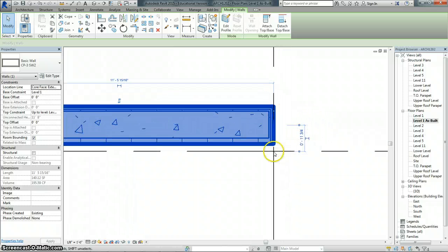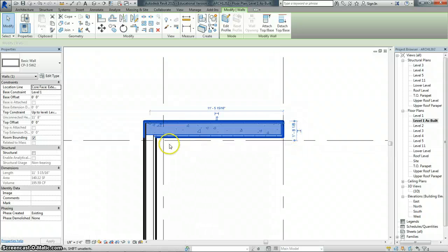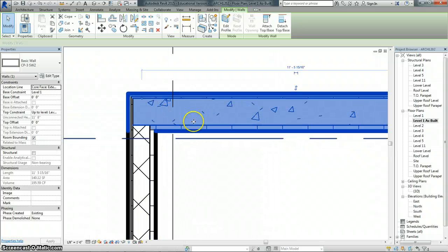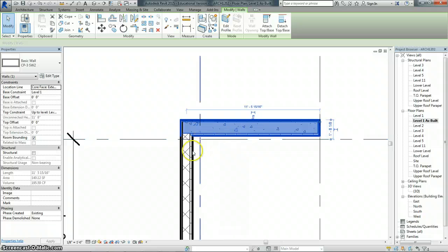Now one of the things we're going to do is a real quick check, because we know that that distance to the outside face does not want to move. So we'll click this a few times, and that still hasn't moved. So the wall has gotten thicker and closer to the inside face. So that's great. So if we know where that needs to be, whether it's the outside face of the structural wall or the final wall cladding, if we make any changes, it will stay in position with the grid.